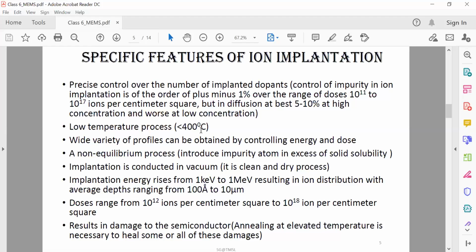Okay, and because of the problem of rearrangement of dopant atoms and further diffusion, which spoils the doping profile that people try to get rid of, a low temperature process is highly desirable. Ion implantation is one of the choice methods of incorporating impurity atoms into silicon.